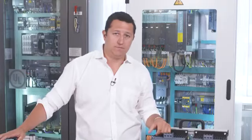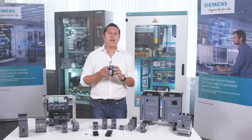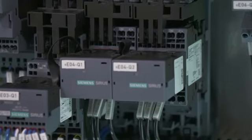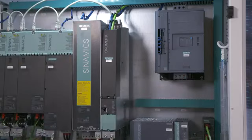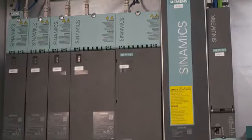And here is where the type-tested combinations get really interesting and help us save money and time. Every single product has been tested for different voltages and has its own short-circuit capacity. Let us make an example. When we talk about control panels, there are always some load feeders that operate motors in different ways, depending of course on the application. We may have direct starters, soft starters, and even frequency drives.